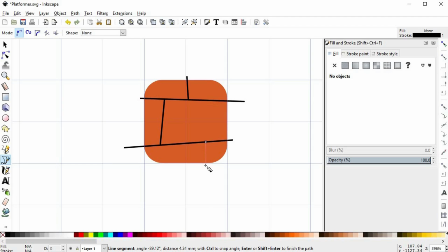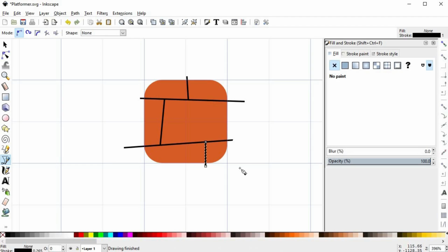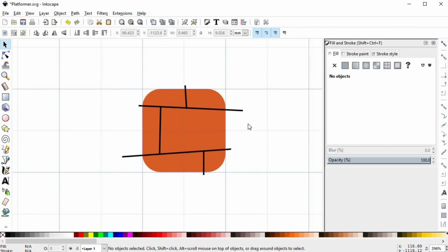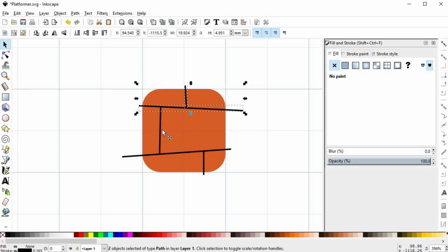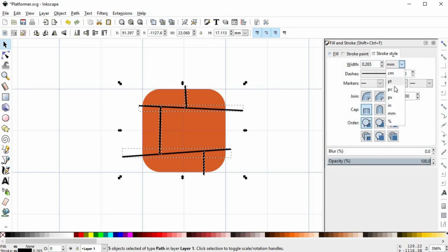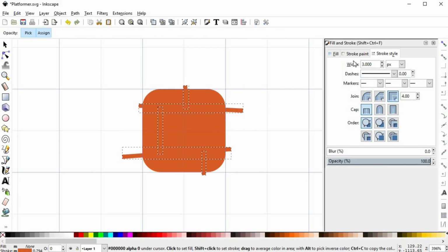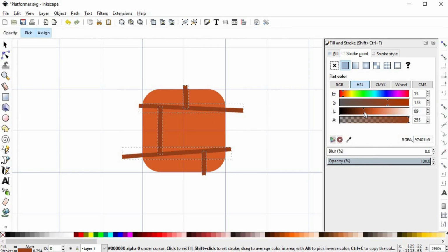Of course, these divisions are meant to be the mortar joints. In masonry, that's the name for the space between the bricks that has mortar. So select all joints and make them bigger with the width drop down. A 3 pixel width worked for me. Finally, give it a darker shade of the local color. By now I think I don't need to remind you the steps.